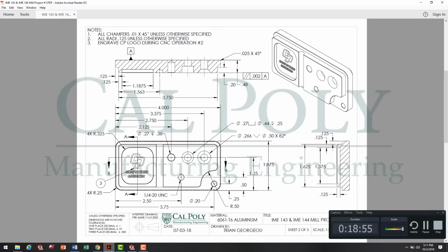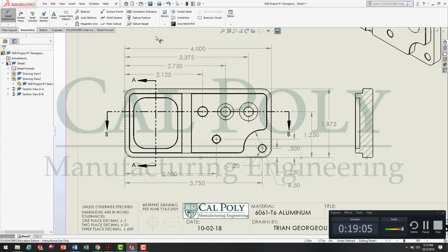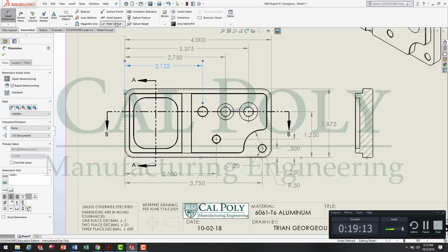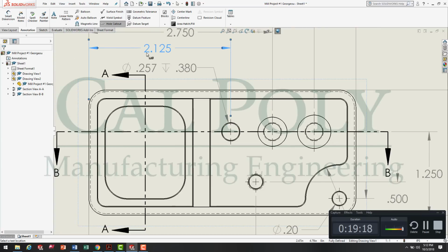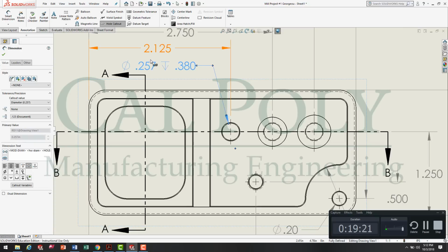Going back to the engineering drawing, you'll see we need to now start doing our hole callouts. To do the hole callouts, we're simply going to use the hole callout tool right up here. Now I know that I've got to move that dimension upwards slightly because the first threaded hole callout, or the blind hole callout, needs to have the depth symbol. And I can shorten the horizontal jog by clicking on that, and I can change the precision of the depth over here on the right.